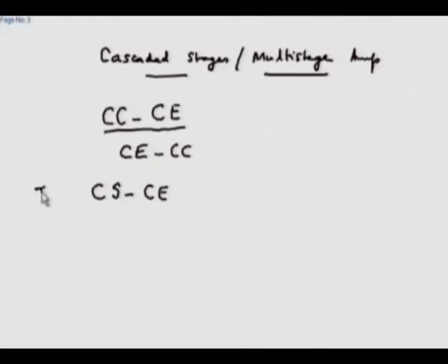You could use a common source amplifier. Professor Mahesh Patil has taught you JFET. Now these days JFETs are not commonly used, but you may be having some of these experiments in your colleges. JFET is an extremely good device. In fact, JFET is the best device in terms of low noise. It is an extremely low noise device. A JFET, as we know, has extremely high input resistance. You could easily have an input resistance of 1 megohm.